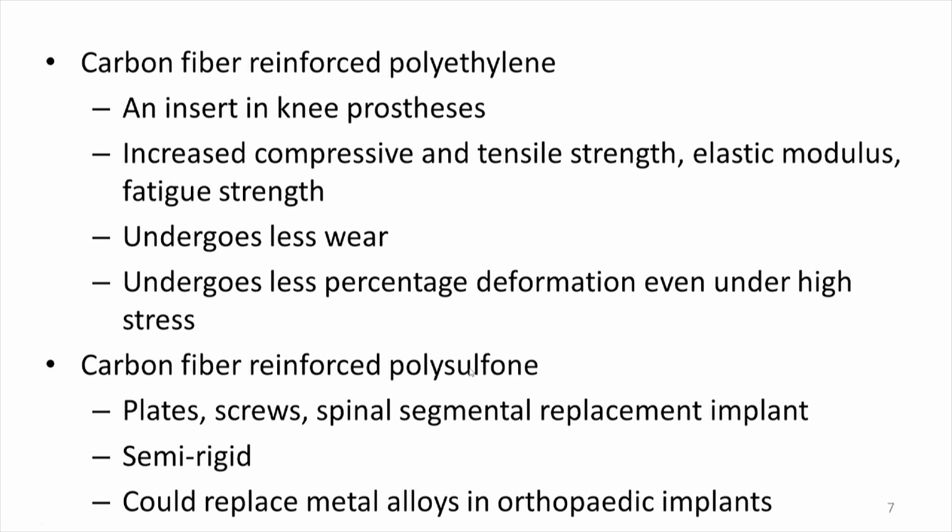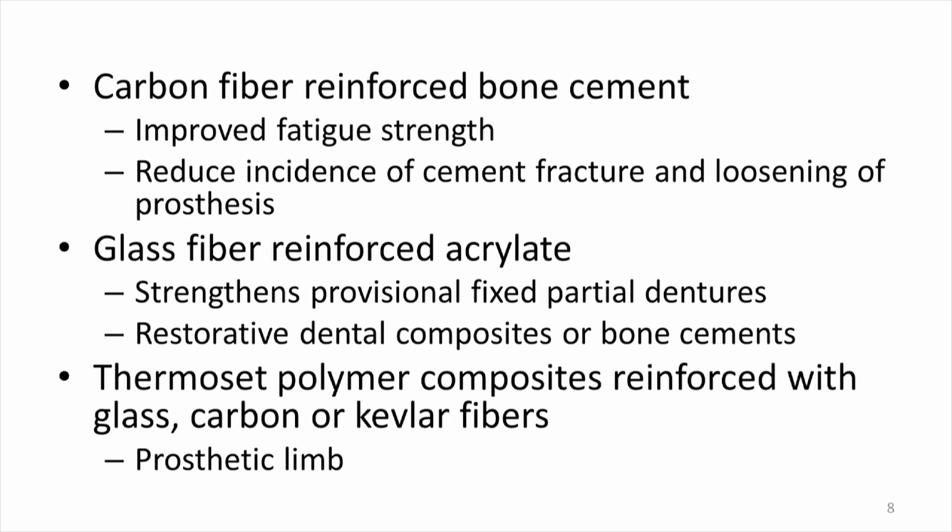Carbon fiber reinforced polysulfone: plates, screws, spinal segmental replacement implants. It is quite semi rigid actually, not fully rigid, but it is not soft like this polymer. It could replace metal alloys in orthopedics. The advantage is it could replace them and they are quite lightweight also. Carbon fiber reinforced bone cement has improved fatigue strength because of the carbon fiber. It reduces the incidence of cement fracture and loosening of the prosthesis.